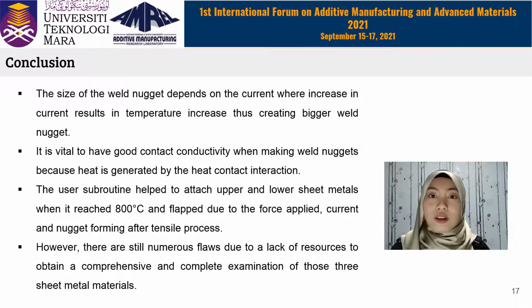Based on the results obtained by varying the temperature in order to form a fine weld nugget, it is plausible to conclude that as the current increases, so will the temperature, resulting in an increase in the size of the weld nugget. It is vital to have a strong contact conductivity when making weld nuggets. This is due to the heat contact interaction producing heat.